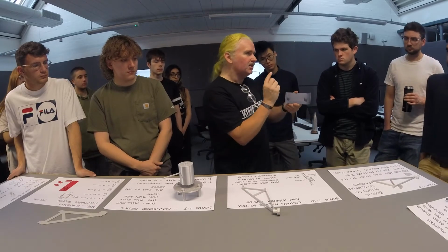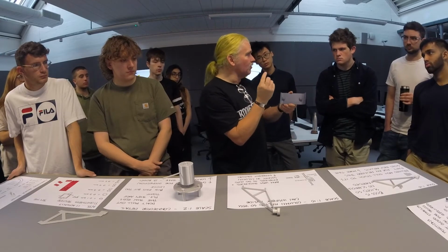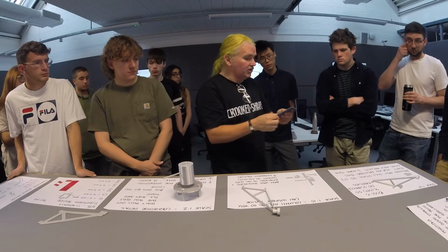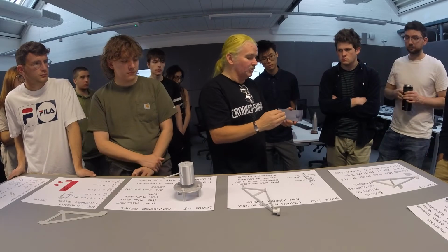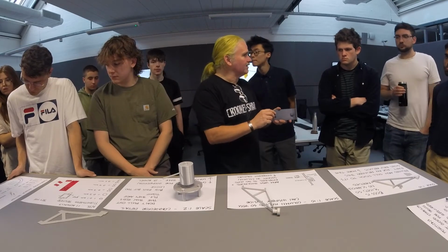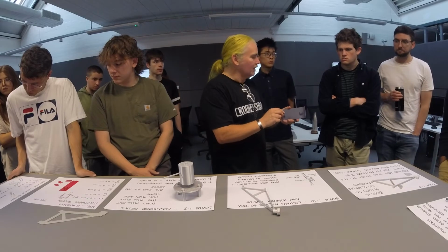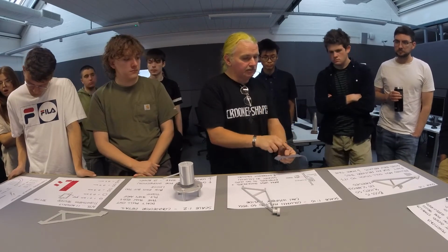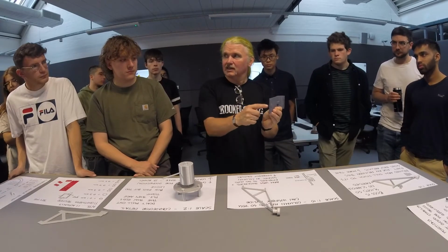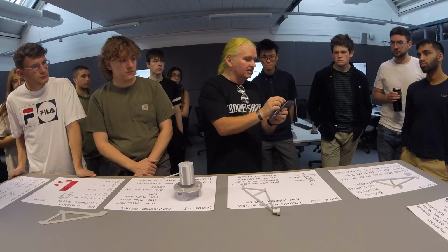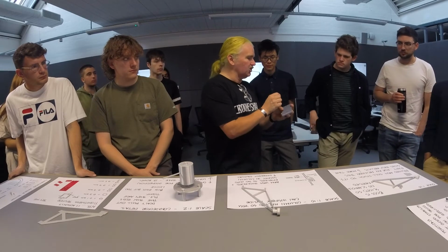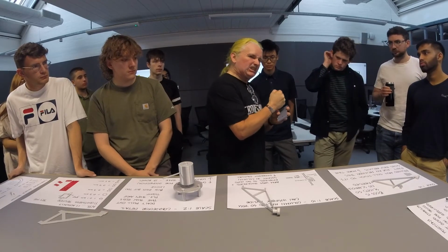It can just make the next print hang over a tiny bit, and it creeps its way out on these angles. Sometimes it does it really well with a bit steeper than say 45 degrees even. You can see this overhang tester here. It's managed at 35 degrees, no problem. But it did need some scaffolding inside the holes, because there's an overhang inside the hole which it had to support. But that's a lot easier than scraping all this off all the way down. So it's just a sharp little screwdriver, and out you come.